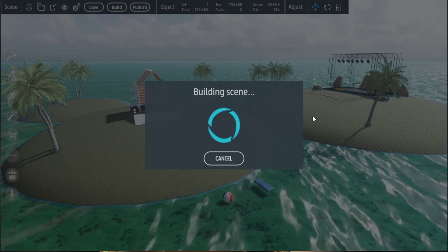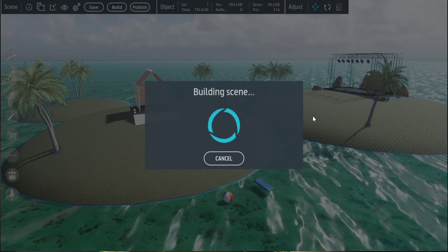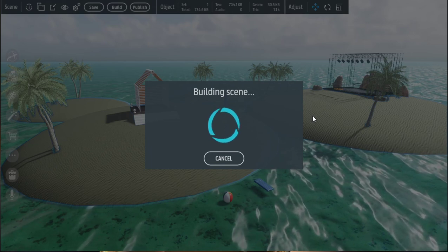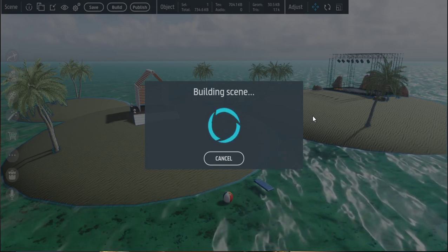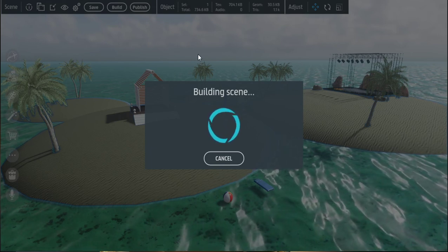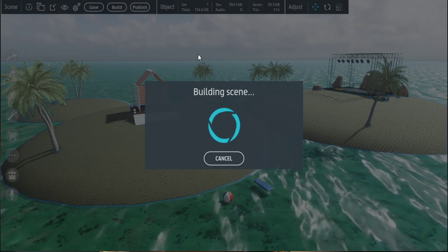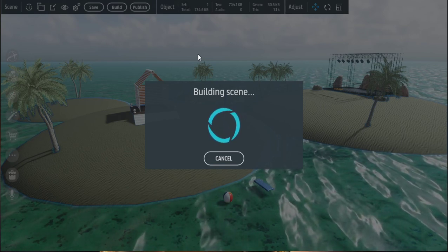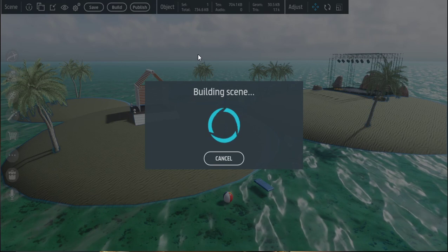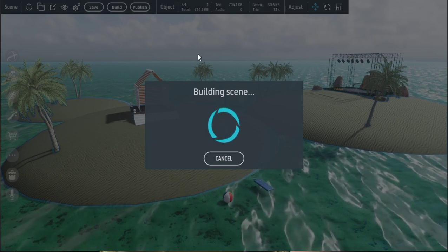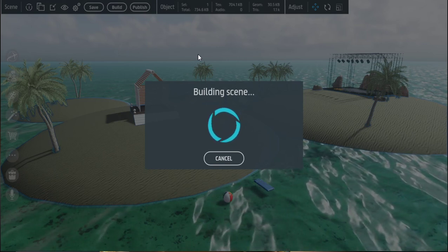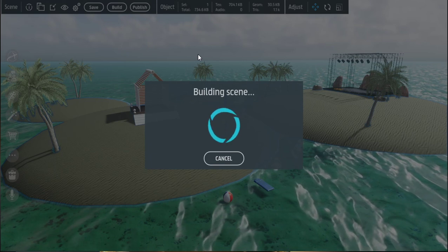So as soon as this uploads here, like I was saying, make sure you have the scene illumination on no processing, okay? And that's in your scene settings. So if you go up here, it's going to be in your scene settings. There's no need to have all the finishing touches on an edited scene. Just get everything the way you want it. Then once you're saying, okay, this world is ready to go, this is the way I want it, then go ahead and hit standard or however you want all the actions to take place in that scene, okay?